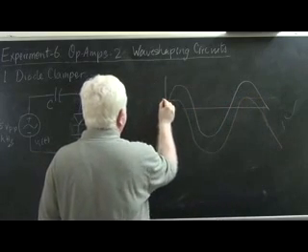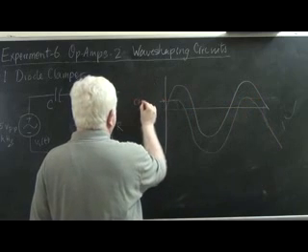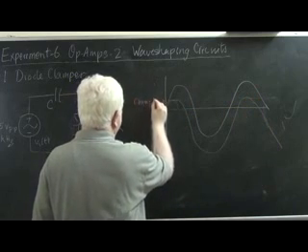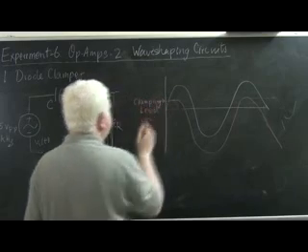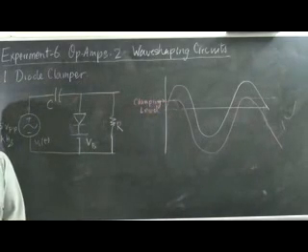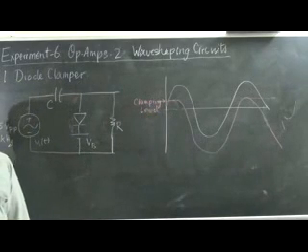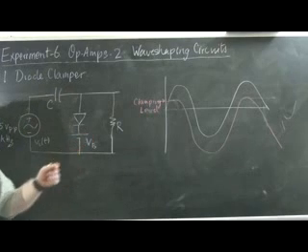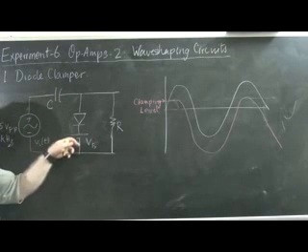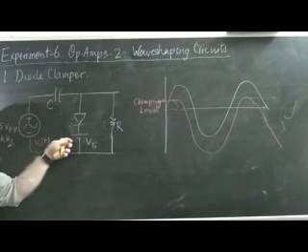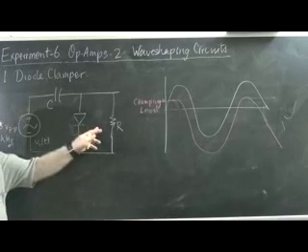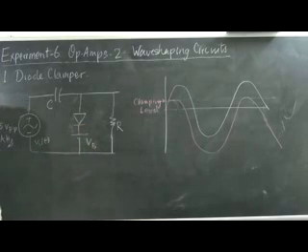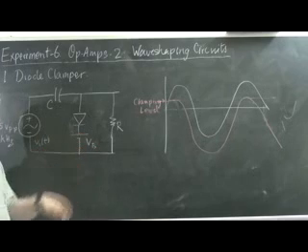So that this becomes the clamping level instead of 0. The clamping level could be made positive or negative depending upon the battery voltage that you set over here for the clamping circuit. The resistor of course remains and serves the same purpose that it did when the battery voltage was 0.